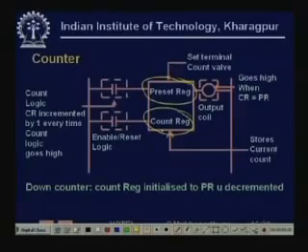But the only thing is that in the timer, the timing register is incremented by an internal clock at regular intervals of time. So the timer is nothing but a counter which counts the timing pulses from an internal clock. While for the counter, you are trying to count something, maybe the number of parts produced, or the number of parts arrived on a conveyor, or something like that. In which case, with every event taking place, you have to generate some kind of a pulse using again contacts and sensors. Now those external pulses will actually augment the count register. So in place of the internal clock pulses which were coming at the timer, here we have external pulses which are triggered by the events that we want to count.